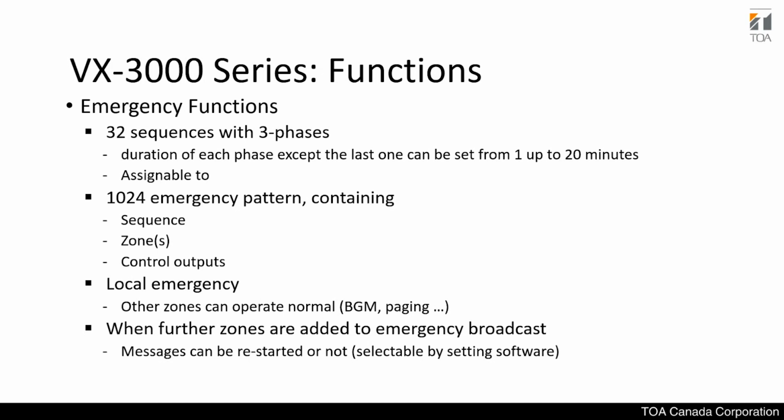You can take the pre-recorded message and set a pattern, so that when a cue or a trigger is initiated, say there's a fault, that particular pattern is played or triggered. Say there's a local emergency that occurs, all the other zones will be overridden, and then the emergency pattern will trigger and play throughout.